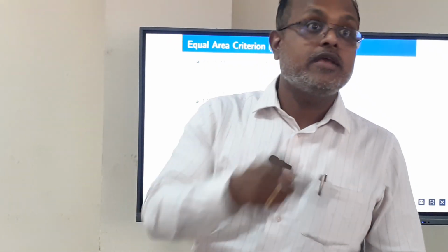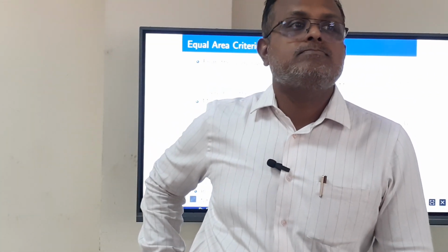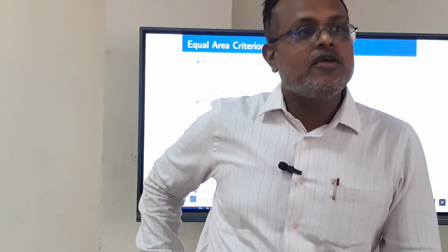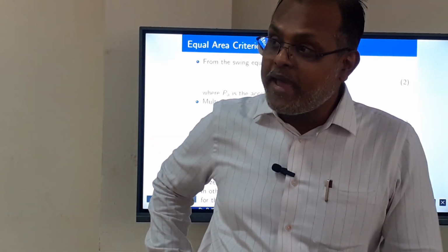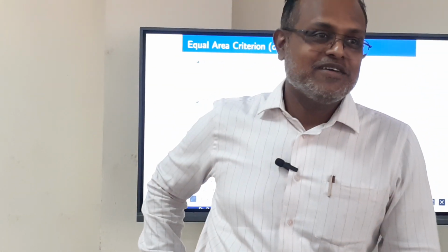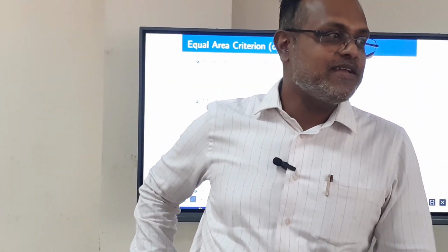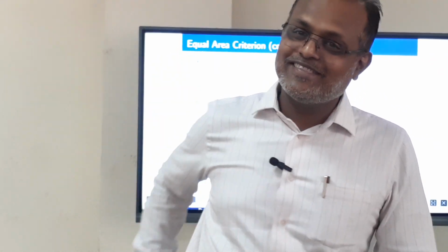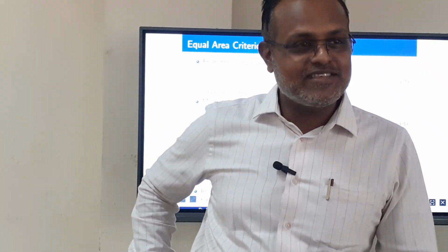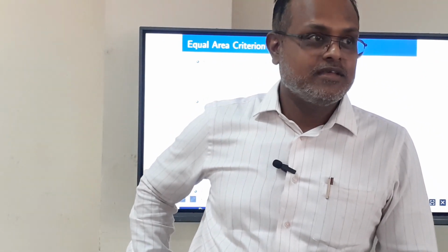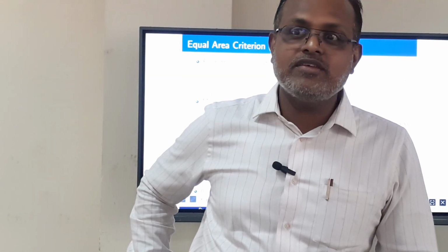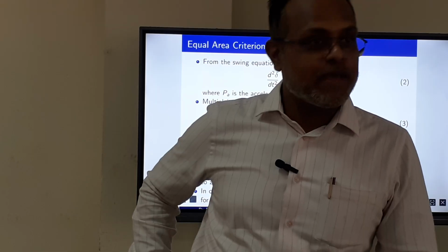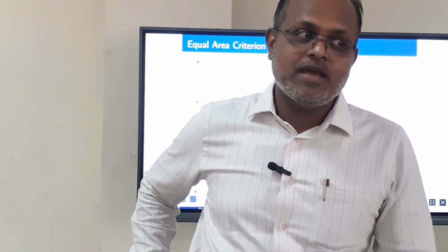Long question. So when we say it goes beyond where it can never come back, is that what we call desynchronized? Yes. When it can never come back, that actually means it will desynchronize for generators. For our case, instability means desynchronize. For a human being, when it goes, it cannot come back. For a generator, it simply means desynchronize. But that's a big thing. One generator desynchronizing can lead to a cascading effect of multiple generators desynchronizing, eventually leading to complete blackout. It happens sometimes.